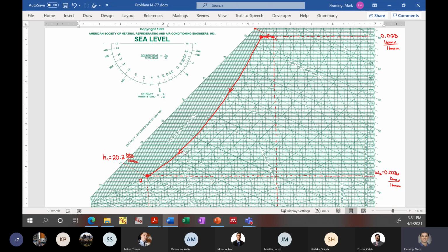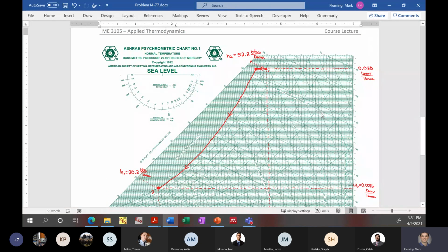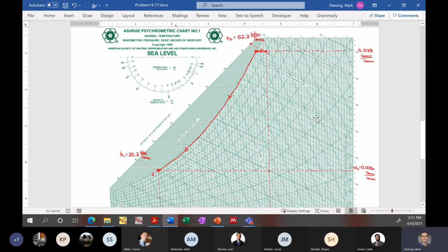And so again, instead of doing all of the calculations by hand, if we wanted to just use the chart to look things up, we could do that. If you have the high resolution charts, which I've provided the PDFs for, you can use those over the psychrometric charts that are in the textbooks. We can make these substitutions with reasonable accuracy at this point. And so that's what I wanted to show with this psychrometric chart. The PDF has been provided for you to use in place of the ones that were included with your homework assignment, which was the psychrometric chart from the textbook.